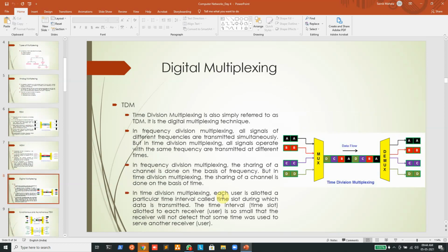Okay. Next, we come to digital data. The previous techniques were for analog signals, which means electrical signals or optical signals. But in this case, if I have a digital signal, remember that we can convert an electrical or optical signal into a digital signal using the various line coding schemes. Now if the signal has been converted into a digital signal, and we want to transmit the data through a channel and divide the channel into various sub channels, then we will use something called time division multiplexing.